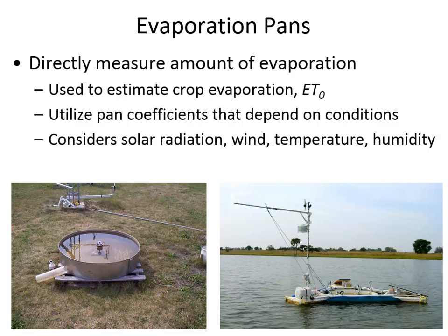And the pan is also going to keep track of all of the factors that we've just been accounting for. We said that evaporation rate is going to change depending on the temperature, the radiation intensity, the atmospheric pressure, the wind, and all of those factors are naturally accounted for by the pan. Think about the wind going over the surface of the pan, the profile of the wind at some elevation relative to the wave height inside of the pan, and the humidity of the air. And so if you want to measure what's happened in the past, a pan can be very useful.